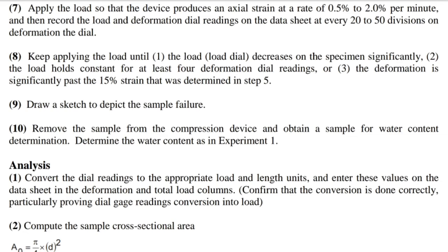10. Remove the sample from the compression device and obtain a sample for water content determination. Determine the water content as in experiment 1.